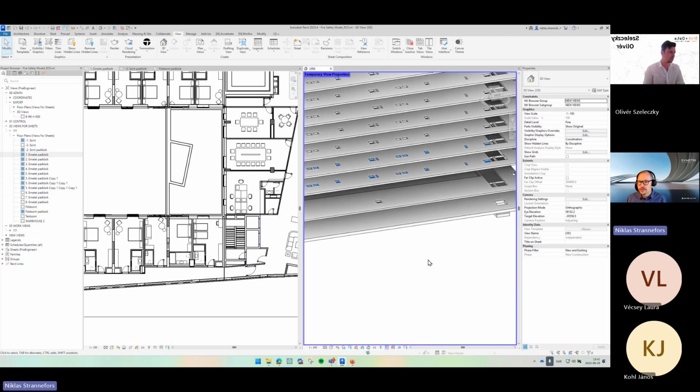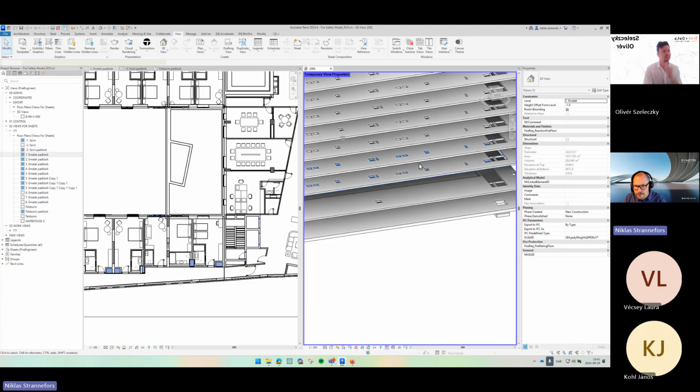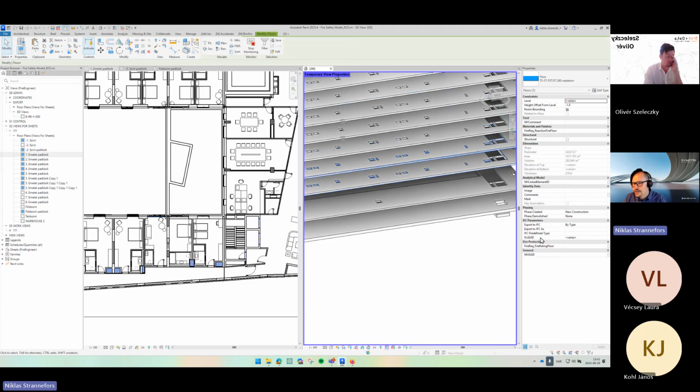The last thing we need to do is, sadly, enter a rating on our walls. I said this was REI 90, so we have a parameter here, fire rating floor. It's not automatic. We just changed the look. So when we copied it and changed the color and the material to whatever requirement we want, all we're doing is setting up the look, the graphics for it.